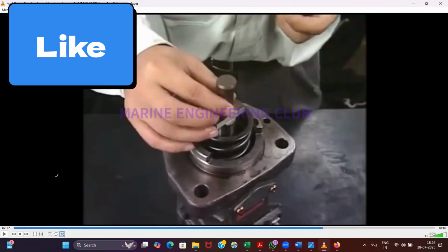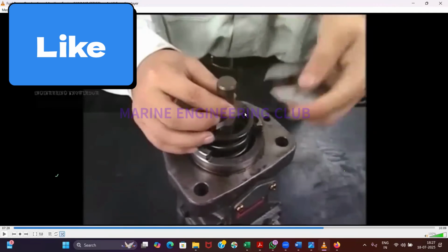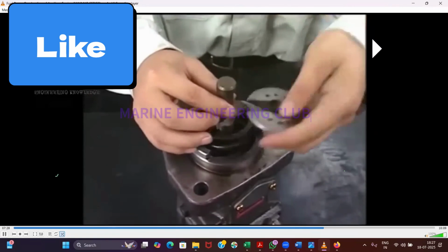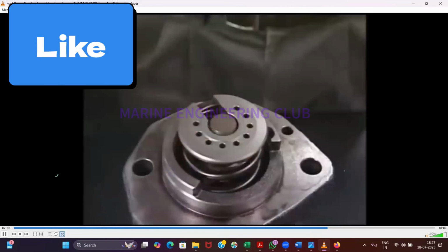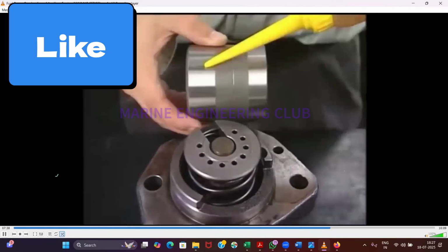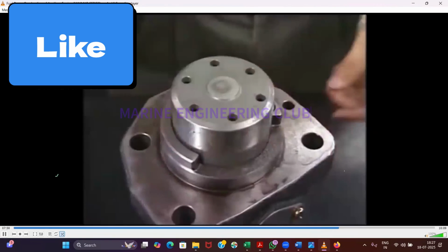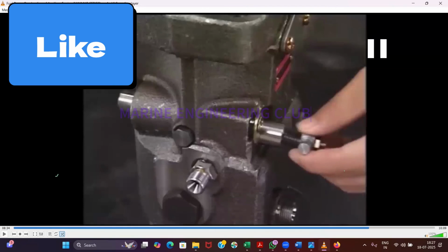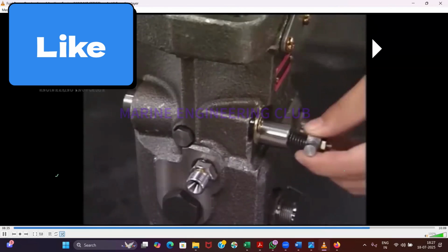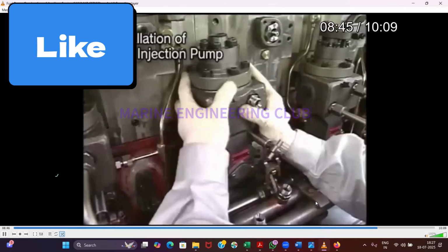Yes, sir. Okay. And this foot, where it is going? This foot, into the control sleeve, right? So control sleeve के slot में जाएगा, and it will automatically match. And then you can put your plunger guide. Okay. And then compress it again and put your snap ring. Okay. That is done. After assembly, just try free hand से rotate करो आपके track को, your plunger should move freely. Okay, now you assemble it back.